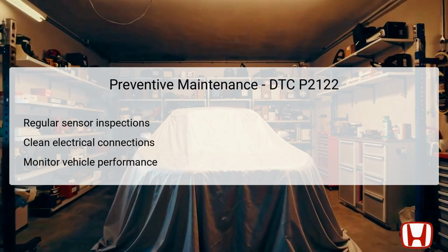Preventive maintenance plays an integral role in minimizing the chances of encountering DTC P2122 in the future. Regular inspections of the Accelerator Pedal Position, APP sensor, and its associated wiring should be part of a routine maintenance schedule, ensuring all components remain free from wear.